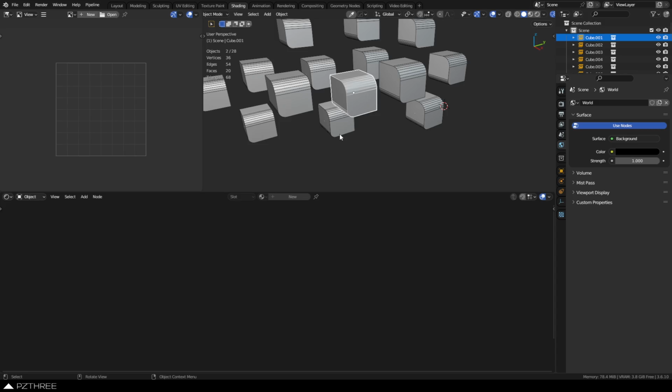So if you wanted to, you could make unique looking objects with their own texture mask, but they use the same base materials. Think of a factory, and you're putting a whole factory scene together. There's a bunch of rusted parts in there. You may need a bare metal, rust. You can start layering those together here inside of Blender. You can break them up with really low resolution RGB masks, and then you can use things like grunge maps to break up how that actually blends together based off of those RGB masks.